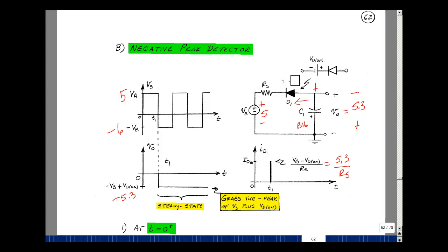Now let's see what happens next. So I get minus 6 volts, which I'll put as plus 6 volts in this direction. The output is still minus 5.3. Let's now find again the voltage across the diode and resistor: this node voltage minus this one, so minus 5.3 minus a minus 6. So we get 0.7 across here. If current's flowing, there's a drop across this resistor, but that would be equal to 0, because I need 0.7 across the diode. So no current flows. We're at a transition point, and the output just stays where it is.